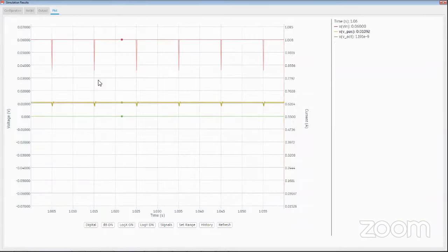And then right here we have the VN, but the VN shouldn't be going like that, unless I did something wrong in the setup of the waveform. We have 10 milliseconds here, but this is going for too short, so I must have put something wrong in the timing of it. It should be low for at least 5 milliseconds. So let's go ahead and fix that.